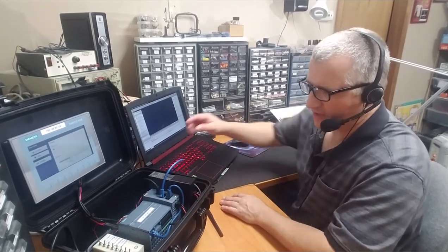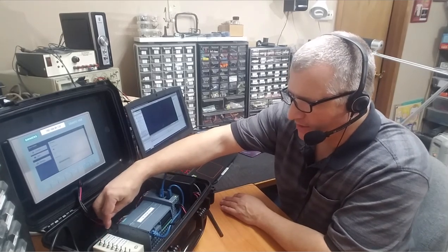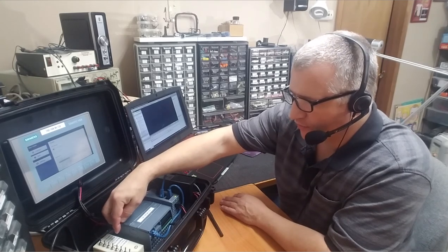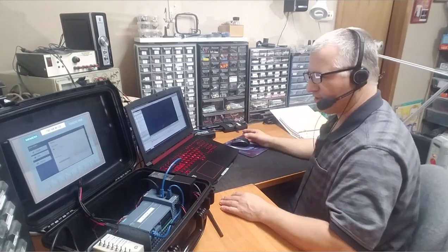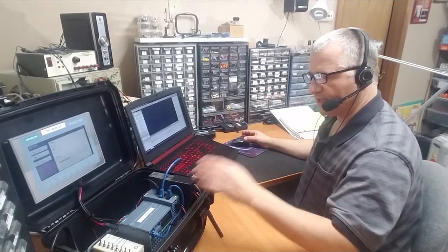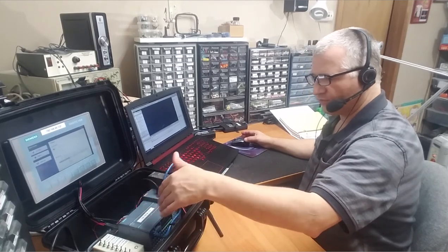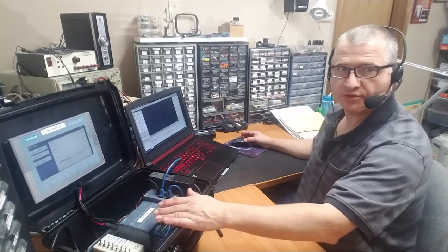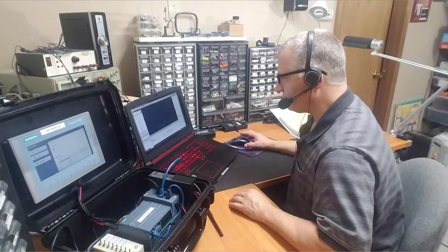But what I've done is I've labeled my inputs here. So I0.0 I've labeled start, I0.1 I've labeled stop, auto for I0.2, I0.3 is manual, and I0.4 is reset. I didn't create labels for them, but the outputs I was originally going to create: on for Q0.0 and auto mode for Q0.1, and it's kind of an arbitrary designation just so I can demonstrate a few things.